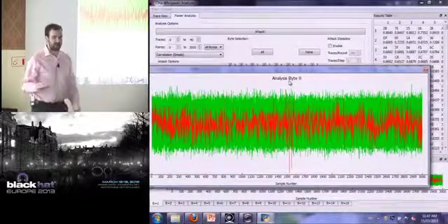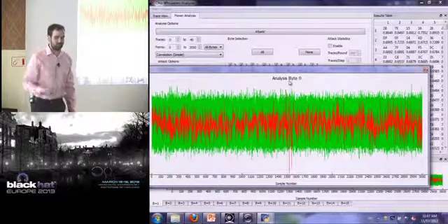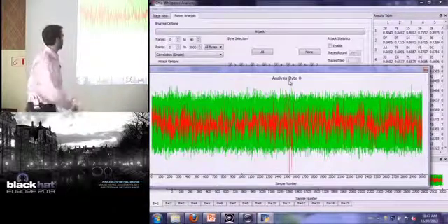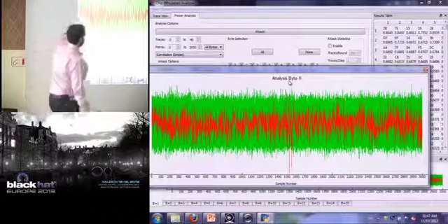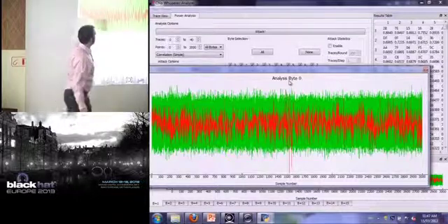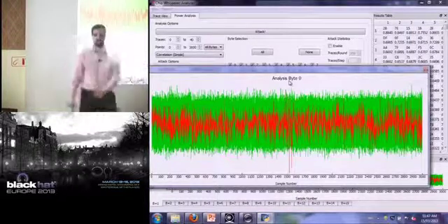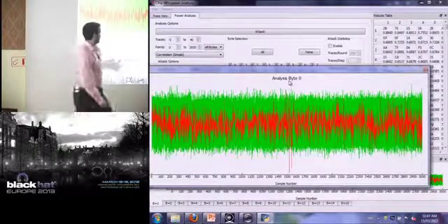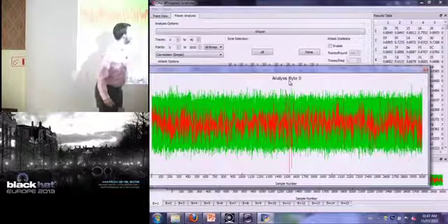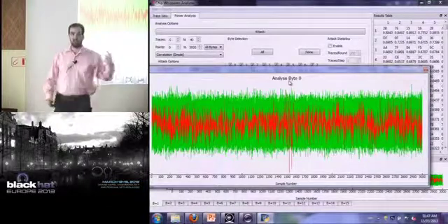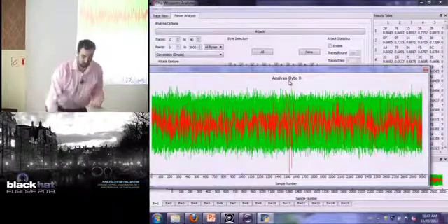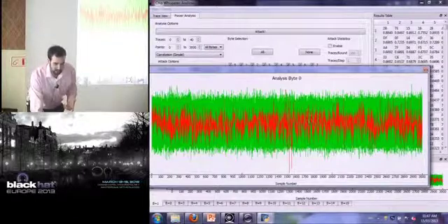And in red, it's highlighted the one that I know to be correct ahead of time, because I know what this key is initially. What we can see is that the red trace at one point all of a sudden has much higher correlation. So this is telling you right at this point in time, this is where that operation actually occurred. So this is where the SBox lookup probably occurred.